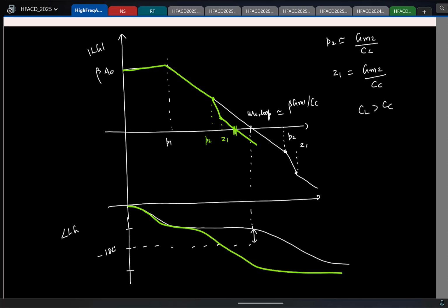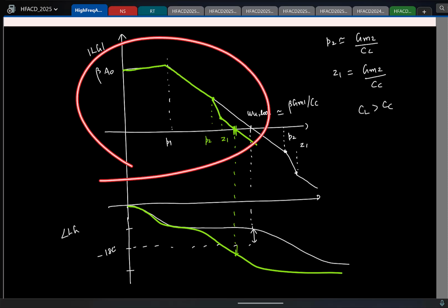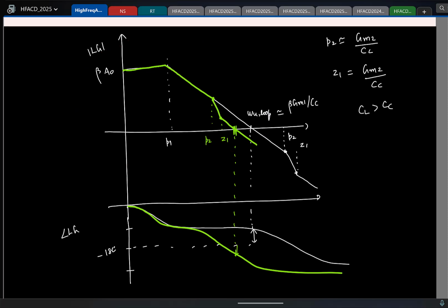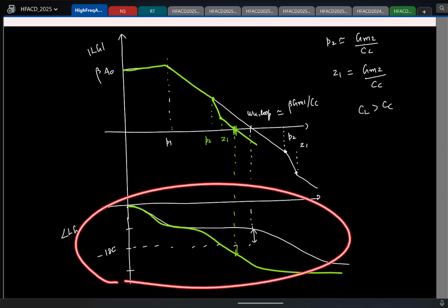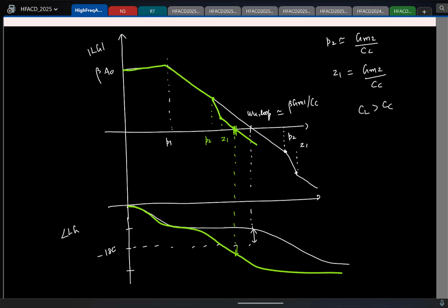So which means now if I look at the phase margin, the phase would have actually gone below minus 180. This will actually be unstable. Okay. So it is not possible for you to blindly only look at the magnitude plot and say, hey, it behaves like a first order system, my system is stable, right? Because significant information is present in the phase plot. You should look at both of them and make a conclusion.